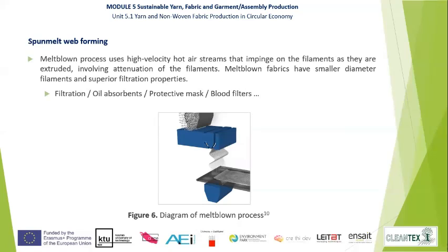And the melt blown processes use high velocity hot air streams that impinge on the filaments as they are extruded, involving attenuation of the filaments. They have smaller diameter filaments and superior filtration properties. They are mostly used in filtration, oil absorbents, protective masks, blood filters.